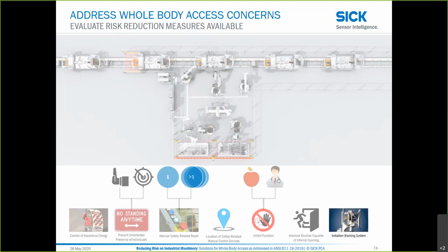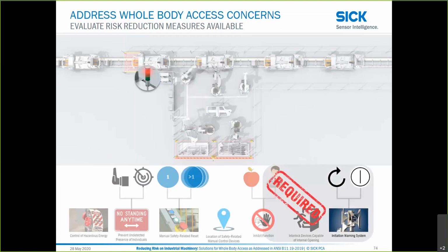Or our last solution is the initiation warning system, either initiating a pre-reset or a pre-start, or both can be used in this application. And keep in mind, if we use a reactive inhibit function or any interlock capable of internal opening, the initiation warning system has to be used with it.